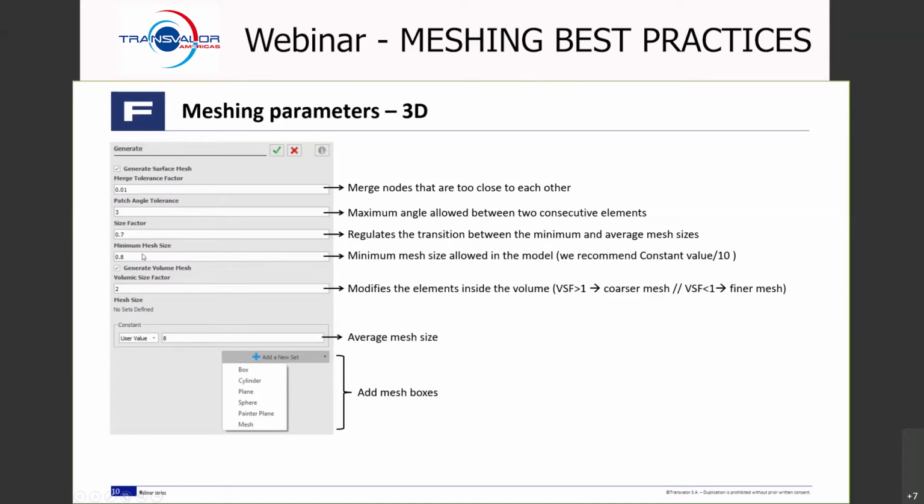As you know, the solver is going to adapt the mesh to the curvature of the model, meaning that if the curvature gets complex, this value of 8 will be reduced to adapt to this curvature. This effect could go on indefinitely, so we need to set a minimum value, so no matter how complex the curvature is, we'll never go lower than 0.8.